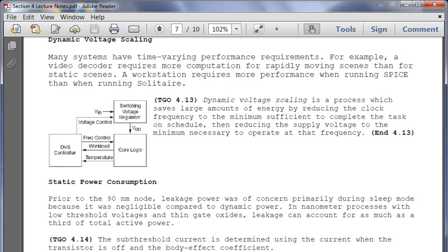Now, Adam, you were talking a little earlier about potential topics. Like, what's this sub-threshold circuit? You can actually use voltage, what's known as body biasing, changing the voltage on the base, to manipulate it so you can get the current to generate through the circuit and create a channel sub-threshold. That's pretty difficult, but if you can do that, it consumes a significantly low amount of power.